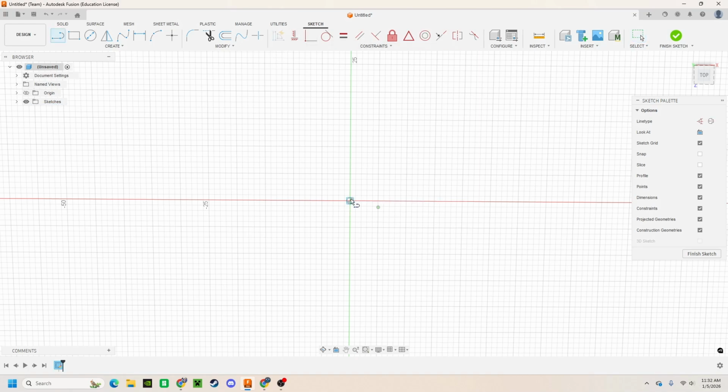So if I make a line where the angle is not constrained and use the horizontal and vertical tool, which is shown here, and tap on the line, it will make it horizontal. And if I make it more vertical, it will snap to be more vertical. And once again, this constraint is automatically applied if you draw the line perfectly horizontal or perfectly vertical, indicated by that blue symbol.